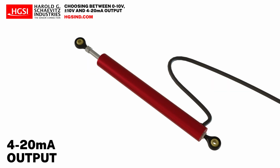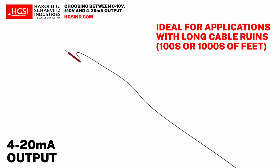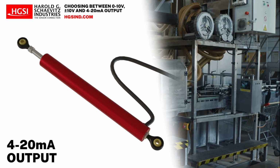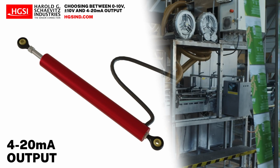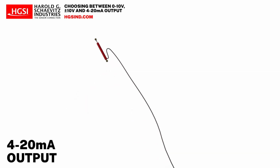Current output is generally the preferred choice for demanding industrial environments. It's ideal for long cable runs, hundreds or even thousands of feet, and for applications with high electrical noise, such as systems with motors, variable frequency drives, or heavy power equipment. Because the signal is based on current instead of voltage, it's much more resistant to noise, and it doesn't degrade over long distances. It's also less sensitive to voltage drops in the wiring.